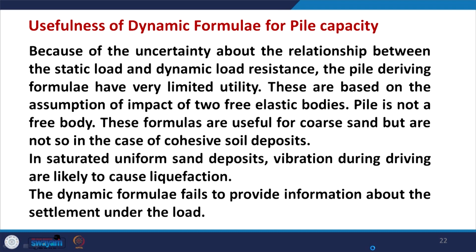They will be able to give you the allowable load or ultimate load resistance, but not the settlement. So this is another limitation, but for settlement the best is to conduct a pile load test, that is the best thing for finding the settlement.